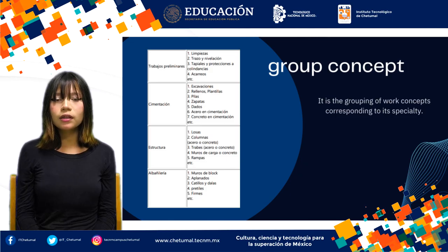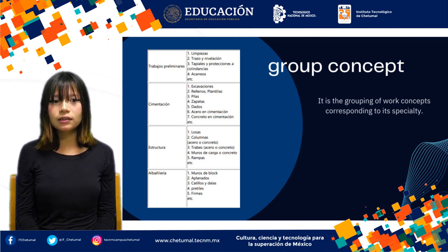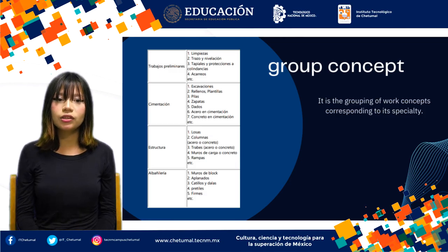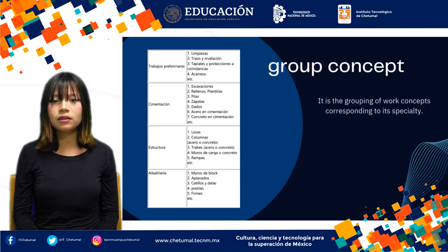Sandy soils. These are loose soils with good drainage, but they lack strength. Deep or reinforced foundations are needed in these cases. Clay soils. These are very cohesive soils that can retain water, making them expensive and challenging. Their load-bearing capacity is low and requires detailed studies and special foundations.